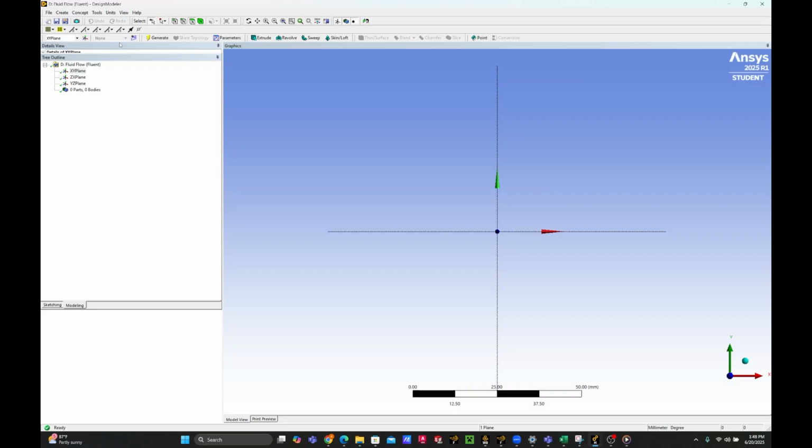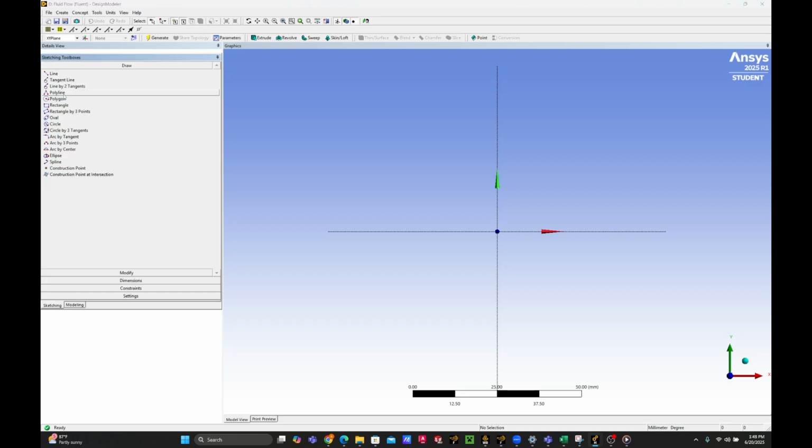And then this part here, I used the polyline tool in the sketching, so I went to sketching, and then polyline, and then from here to there, and then from here to here, here to here, here to there, and then there, and then there. And then I right click, press close end. This way I have all of it. It might look a little crazy right now, but we're going to give it dimensions and then constrain it to be symmetrical across the x-axis.